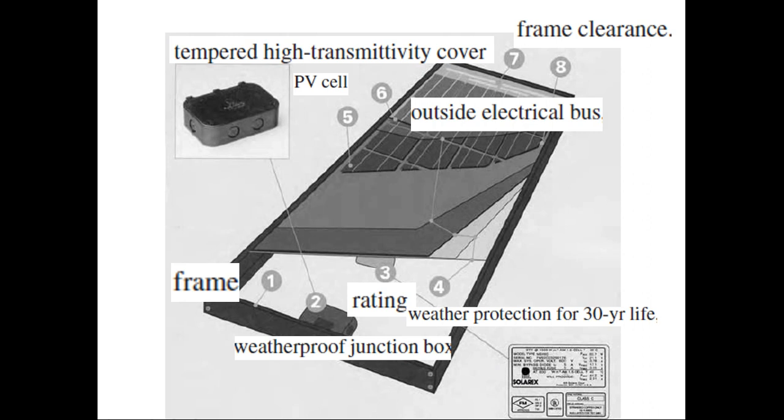From that you will be able to know the voltage rating of the module, the open circuit voltage, MPP voltage or rated voltage, short circuit current, and MPP current or rated current of the module at standard test condition, and how much voltage it should withstand and in which tolerance band. That is to be incorporated on the back side of the module. It might also carry the name of the manufacturer.